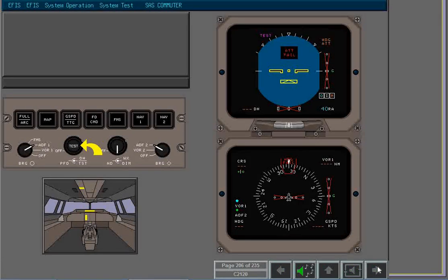During the system test, the flight mode panel push buttons illuminate and a level 2 alert is generated. A symbol generator fault is presented on the overhead avionics panel. 2 seconds later, a compare attitude warning is presented on the central annunciator panel.